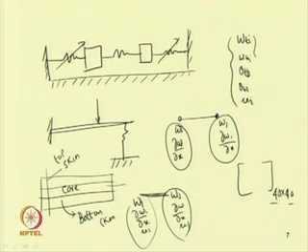So at the ith node one will have 5 degrees of freedom, and similarly at the jth node again 5. So it is a 10 degrees of freedom system for an element, and taking several elements one finds a large number of equations of motion.